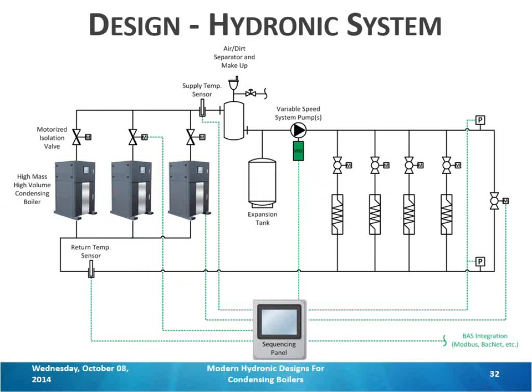And with most condensing boilers, they're more efficient at low fire. A good control package will actually raise the firing rate of the first boiler slightly until it equals 2 boilers at low fire, and then bring on the second boiler and drop the first one down to meet the in-between loads. Otherwise, if you turn on one boiler and you bring on a second, but that load is in between the 2 stages, that second boiler just cycles on and off constantly.